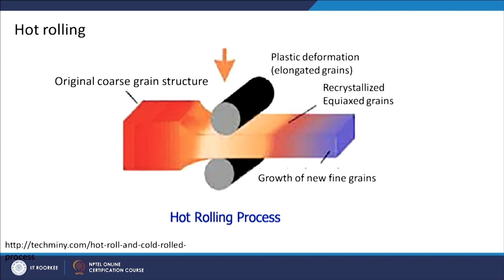The idea is that you have to keep reducing the size of the billet, size in the sense of cross sectional area or the thickness of the sheet. After casting, what you get is big billets or ingots, and those ingots have to be processed initially, and you want to impose very high strains to break the dendritic structure.